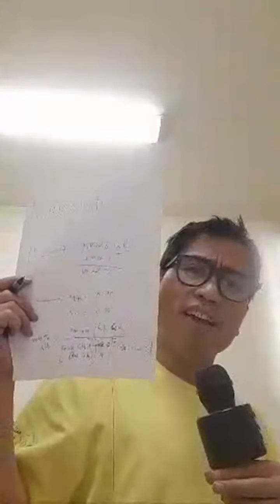Or what is this now? It's the mass fraction, because it now involves the molecular weight. So, the mass fraction of benzene, which is XDB. It's just XDB. So XDB is equal to the mole of benzene, which is 95 mole. I'll go straight to it since it's tiring to explain. So, 95 moles times the molecular weight of benzene.